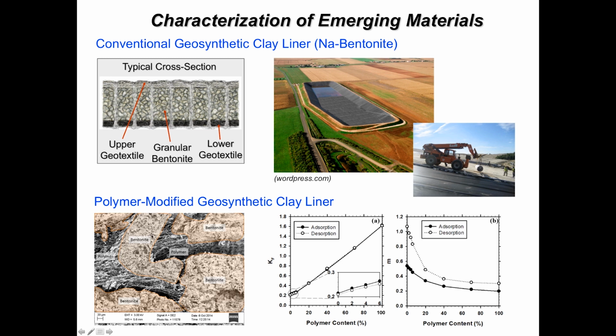By incorporating polymers into this blend, what the polymer is doing, you can see in these SEM images, is that even if the clay clusters within this system collapse, the polymer is available to fill up that larger scale pore space and create a hydrogel that reduces hydraulic conductivity.